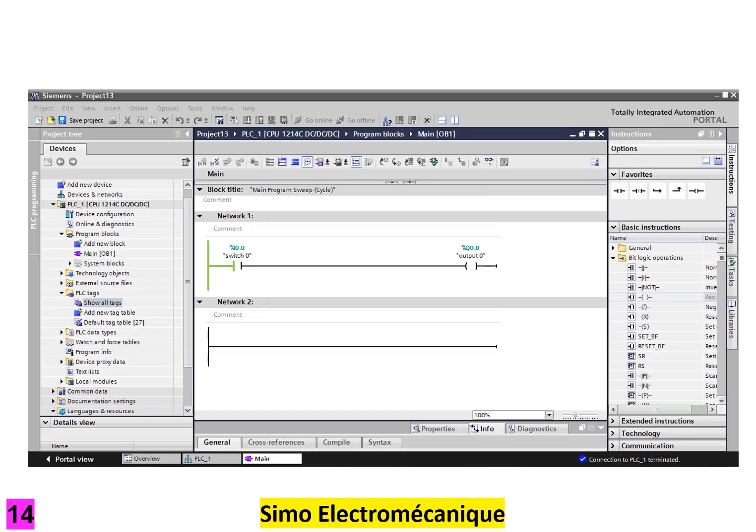Without switching input 0, you can see that the left-hand part of the rung lights up green. This means that the logic signal, or electrical current, cannot pass the switch. If we now toggle the switch on input 0, logic or current can now pass the switch. And because the output is a normally open output, if it sees a logical 1, or the presence of current on its input, it will switch on.